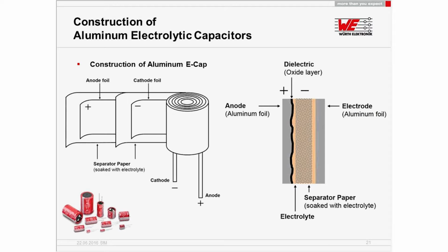Also, what is problematic is if we turn the polarization. You can say it's a half-conducting material, so an oxide layer. What really happens if you apply the voltage in the correct direction is that you can use this product as a capacitor. But it's problematic if you switch the polarization. Why? Electrolysis in the product will start, so the oxide layer would grow.